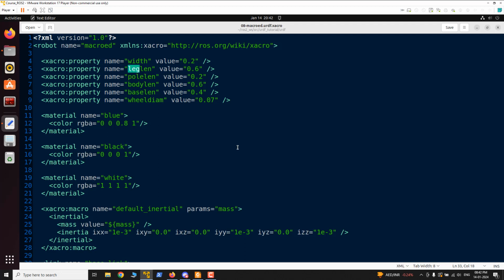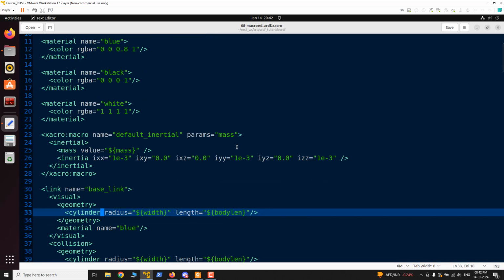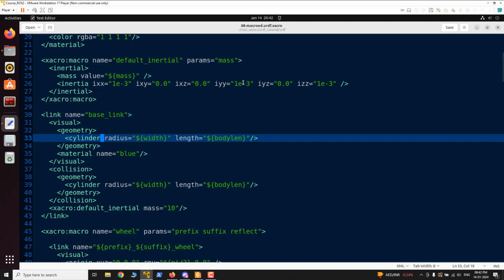The converted URDF, you can modify to Xacro, because if you want to add some things after the conversion, I think Xacro will be better. So after converting from SolidWorks to URDF, in order to do some kind of customization, it will be better if you can modularize it, but it will take time actually. But if you are lazy enough, then you can go with the existing URDF and then add the stuff. But when you try to add some new stuff, it will be somewhat difficult.